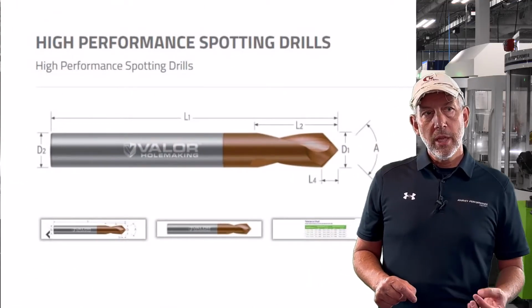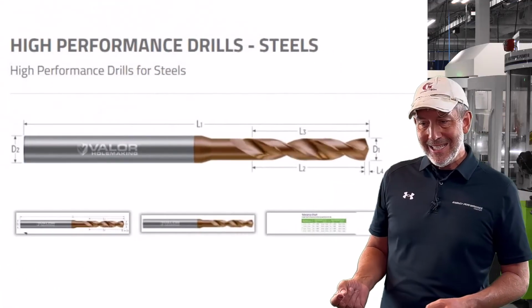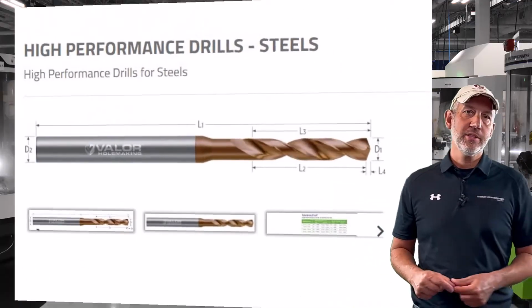So Don, let's just say we're not getting a straight hole, and we're not having those features. Well, first of all, a lot of people also ask, should I spot? Should I pilot? Should I do all these features? Now let's just explain what spotting is and what piloting is. So spotting is very different from piloting.